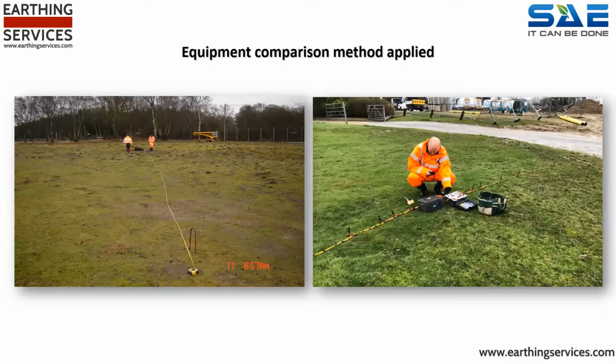The second photograph demonstrates an engineer using application-specific manufactured test leads. These comprise multiple cables cut to specific test distance lengths, terminating in a connection point for the test probe. Multiple test probes are used here, with each distance of the test having its own test probe. The test leads terminate in a switch with the dial, whereby specific test probes will be activated to obtain a result for that specific distance.